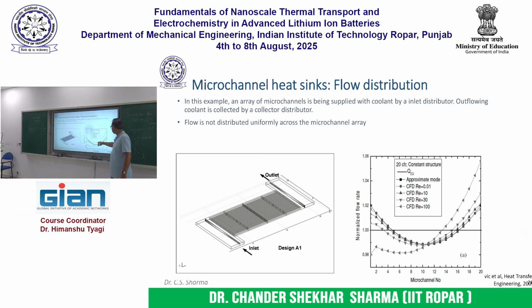So here this curve indicates uniform distribution of flow, where the normalized flow rate is plotted against the microchannel number. So instead of a uniform distribution, you have non-uniform flow distribution with less flow near the center of the microchannel array, and more flow towards the boundaries, okay. So this is not ideal, right.